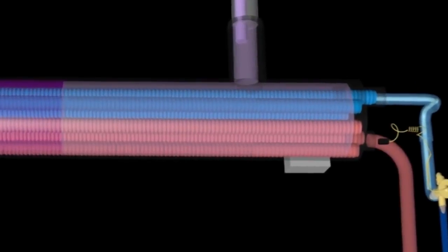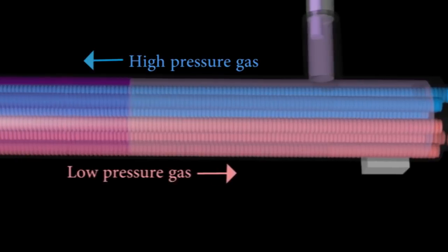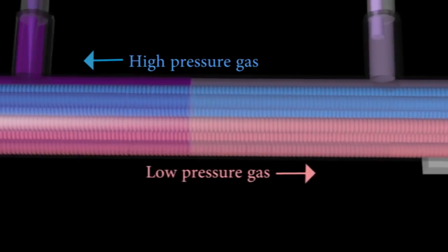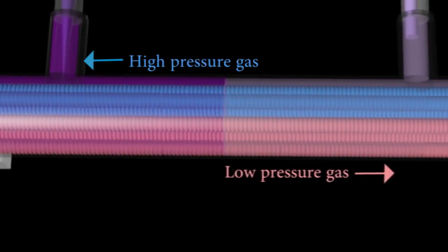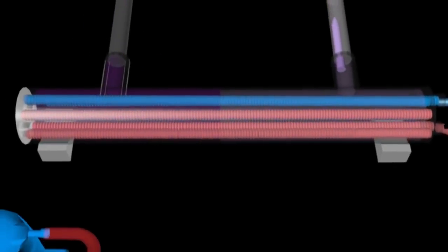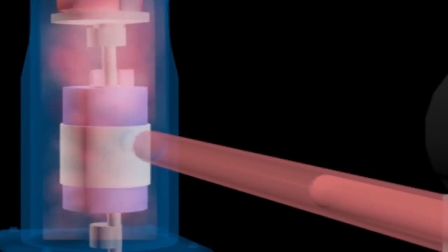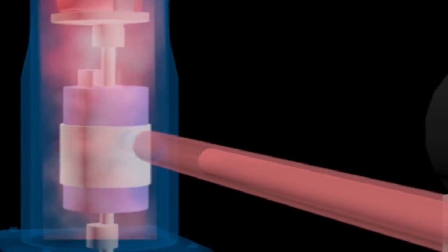low-pressure gas. The evaporator most commonly used is the shell and tube type, where the refrigerant flows in the tube and the water floods the shell. The evaporator is covered with insulation to reduce heat transfer. The refrigerant in low-pressure gas will return to the compressor and continue to the next cycle.